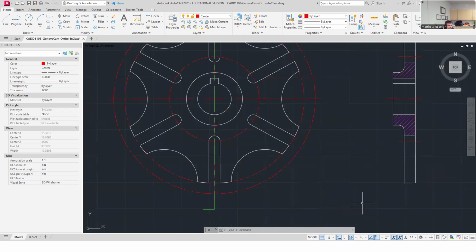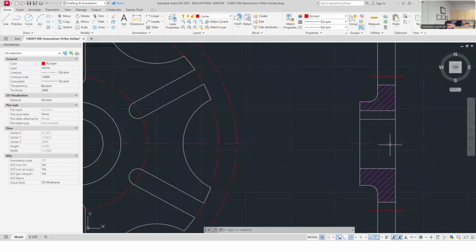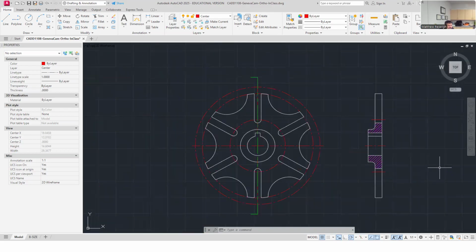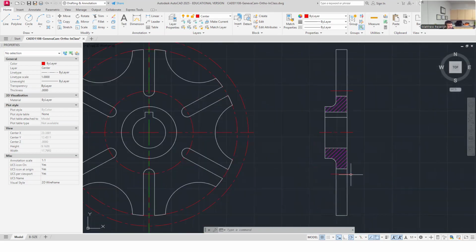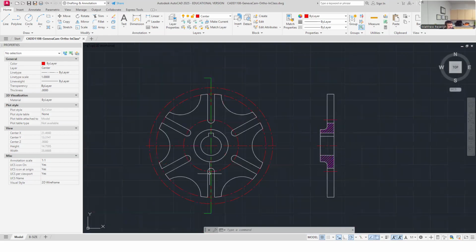These three I feel like are the most necessary center lines on our section view, with this one being the most essential. The section view is confusing. This helps me identify that there must be some radius feature of this surface that I'm looking at. And so this is communicating that there's a radius feature here, and the center of this radius is here. Okay, enough of that.